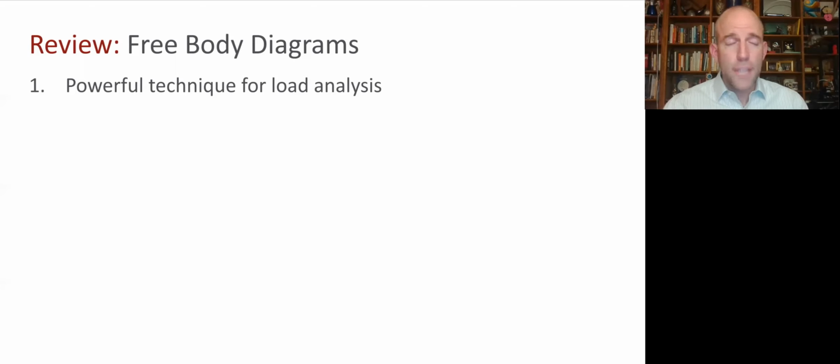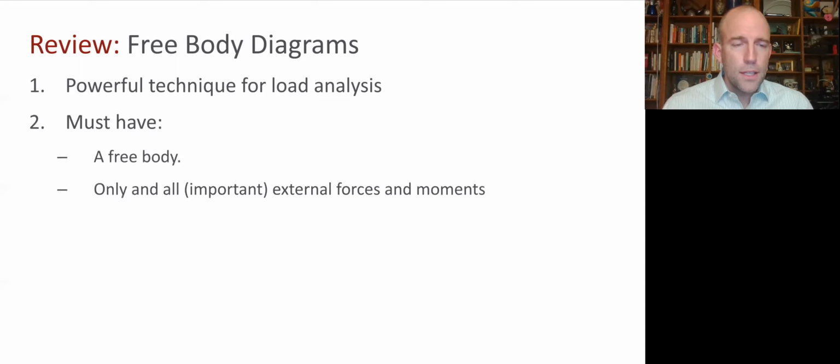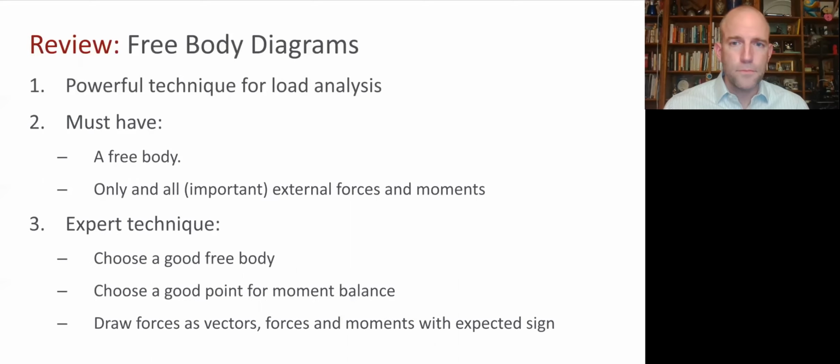So free body diagrams are essential in mechanical design, and you're going to do a lot of them. So it's worth investing the time to become an expert. Now, when you're doing a free body diagram, you need a free body. That kind of sounds obvious at first, but it's good to be explicit about it. What is inside and what is outside of the body that you are analyzing? Always be really clear about that. And you want to include only external forces, no internal forces, and ignore the small ones to keep things simple.